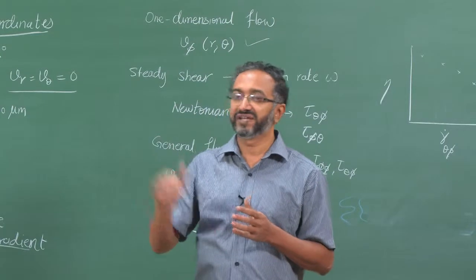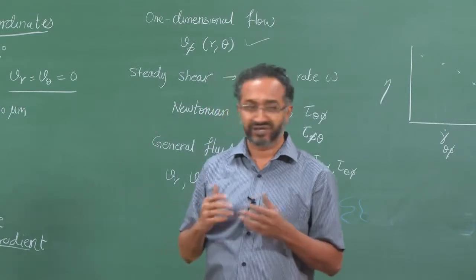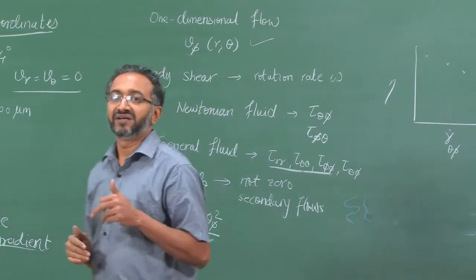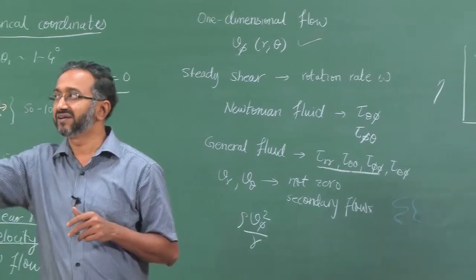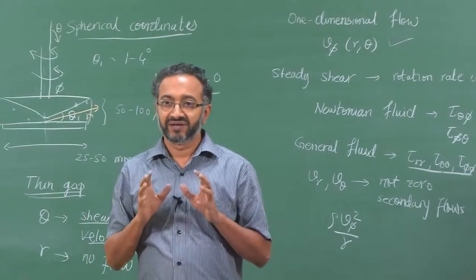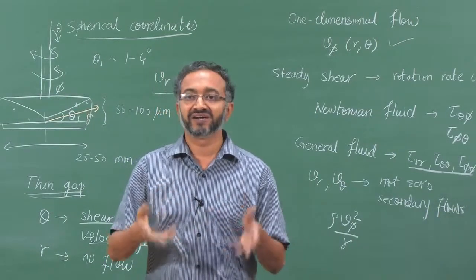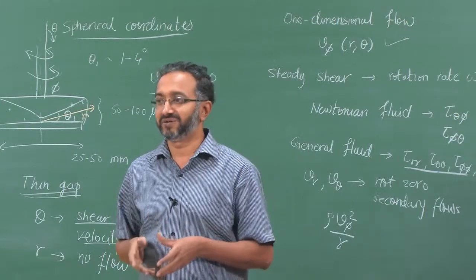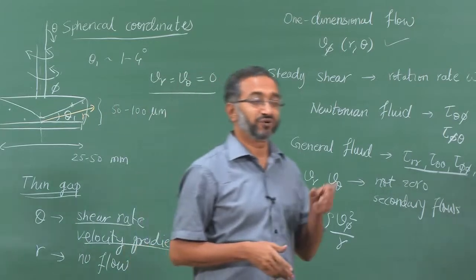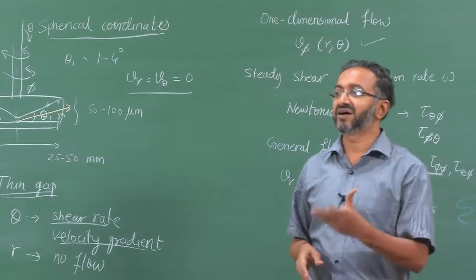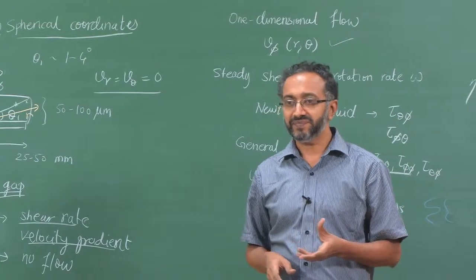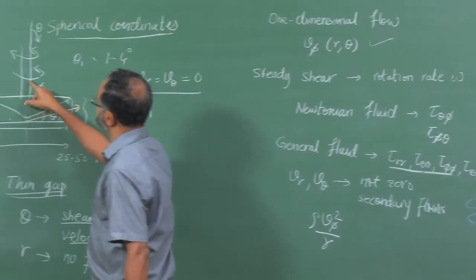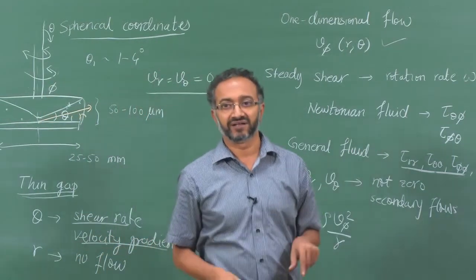So, whenever there is a control variable and a set point given to an instrument, it will try to meet that. Now, how fast does it do it, and is there an overshoot and then settling of that value? If you are making a measurement during this period, you will definitely get artifacts, because you are measuring in fact the instrument capabilities and not really the material behavior, because material behavior can be measured only when omega has become constant and gamma dot theta phi has become constant. So, even though we are assuming that the fluid layer here is at constant omega, we have to make sure that the instrument itself is able to rotate at omega.